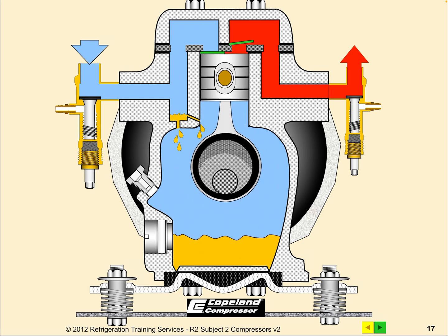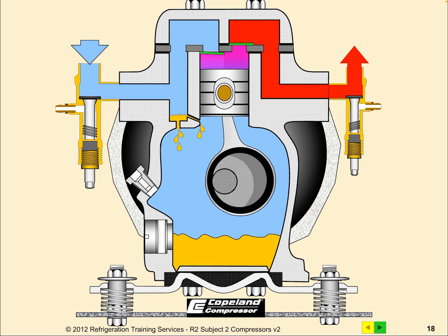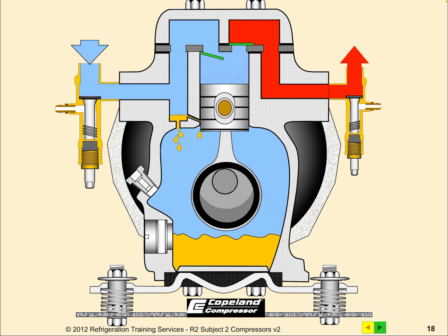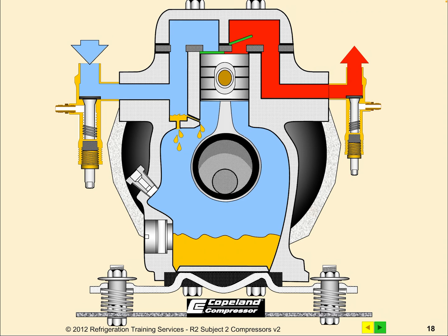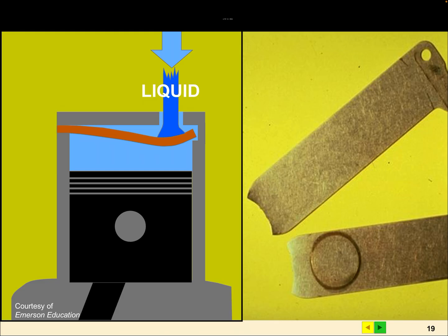And there's always that little, let's call it delay or change, where there's nothing going on because of the re-expansion, of the inefficiency. And that's very difficult for reciprocating compressors to minimize or to eliminate. So that is just a characteristic of these systems, and every system will have a certain amount.